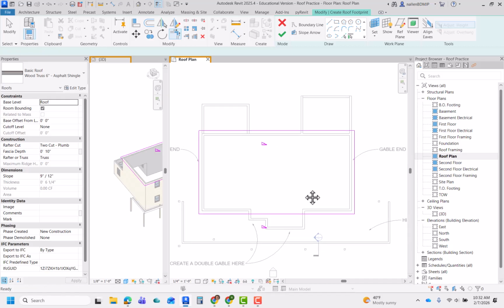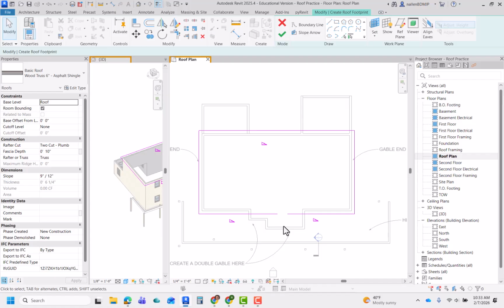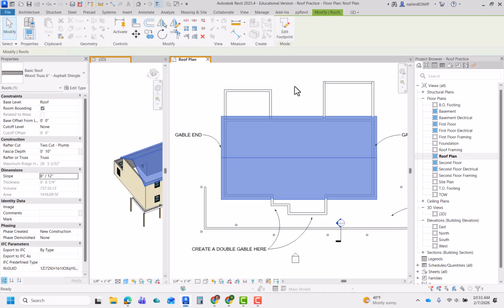And if I find that I need more lines, I can always come back and add them in later. In fact, SL, the split tool, is great if you decide that you need to somehow separate some lines that are already there. But for now, I've got my 4 lines, and over here it says that I've got a 9/12. Let's go ahead and try it out at an 8. And I'm going to hit the green check mark and see what we've got.